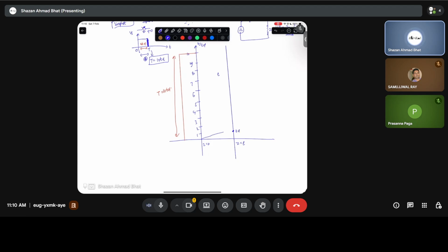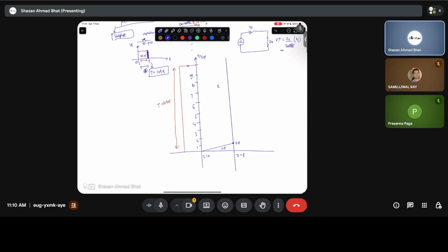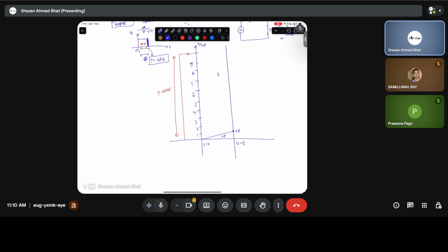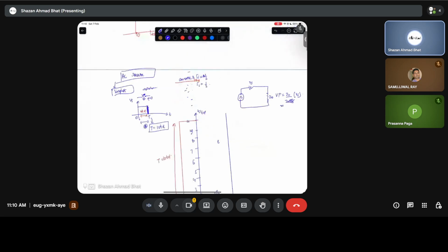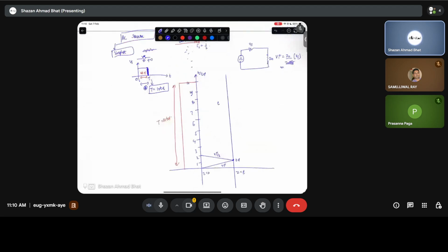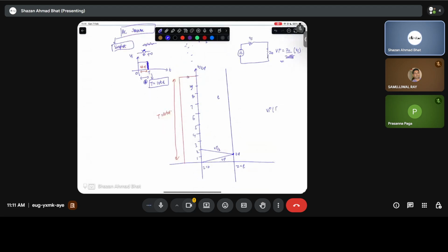Okay, so initially the voltage will rise, as you know, governed by V1 plus. This will be V1 plus, which you can compute simply from this particular thing. Now after 1 TD, you know that the voltage is going to get reflected. How much will it be? It will be this V1 plus divided by this particular coefficient, and this is basically V1 plus into the reflection coefficient.